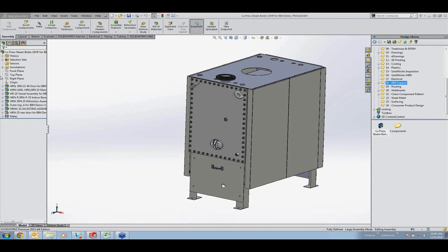Well, now I can add those to the favorites folder here, and in the favorites folder I can go ahead and create a subfolder. And in this case I can name it weld prep. Then in different configurations for my model, I can easily suppress all the weld prep features if necessary.